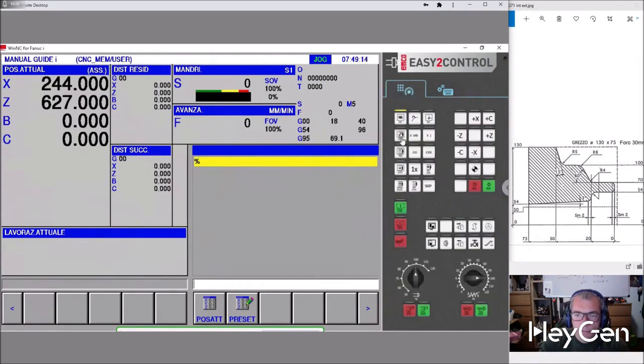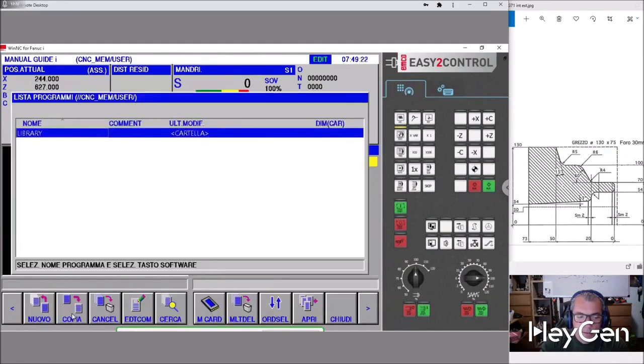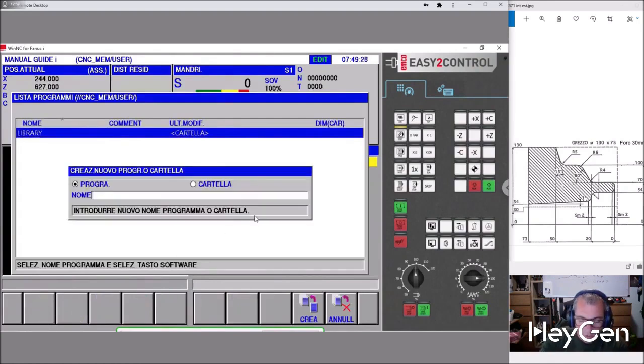Once again today, the very first thing we need to do is enter edit mode. Edit happens to be precisely the area within CNC operations allowing me as an operator to manipulate these programs. Going over to the Program List view, we can see our machine is currently in a virgin configuration. So let's proceed to create a brand new program, calling it simply G71.